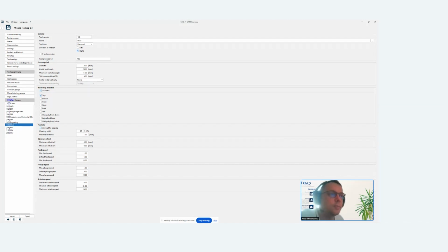As you can see, the post processor ID in here is the tool ID which the CNC recognizes. Each type of CNC machine has a different ID number, but we can configure that once the client sends us some example files, then we can find the information.